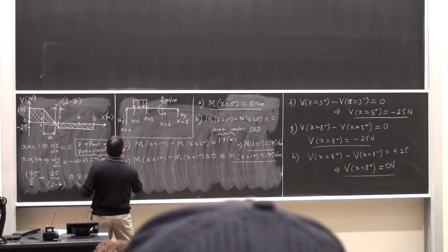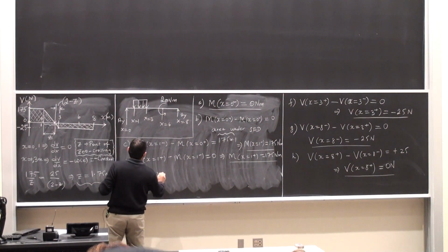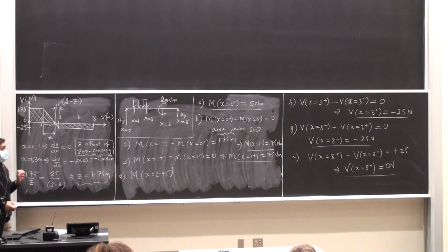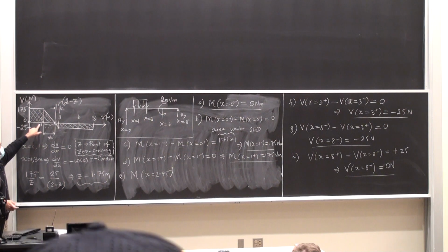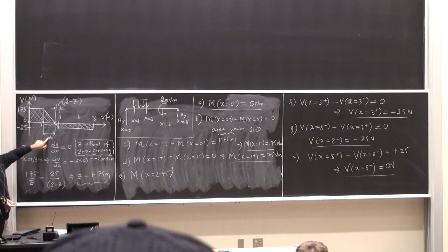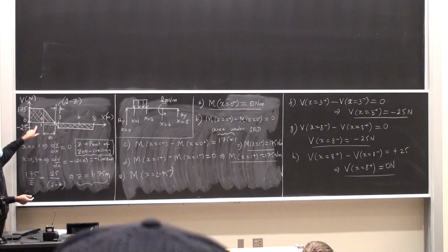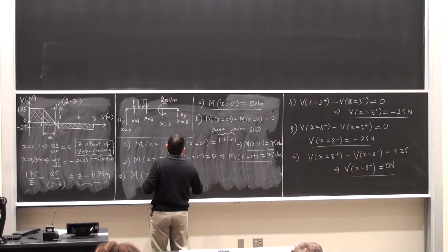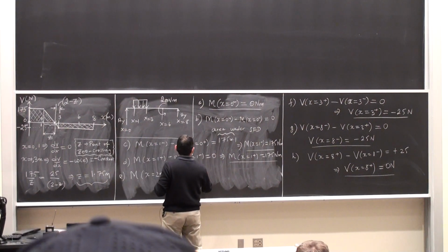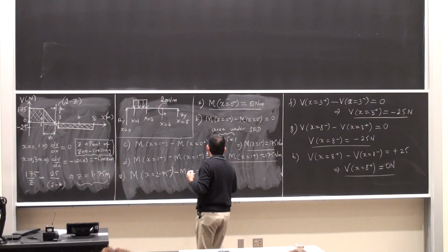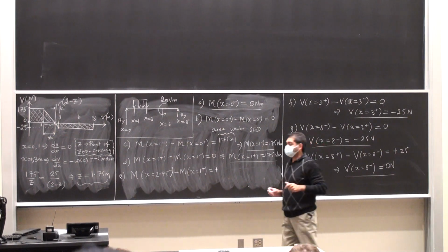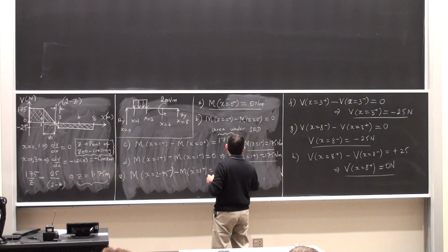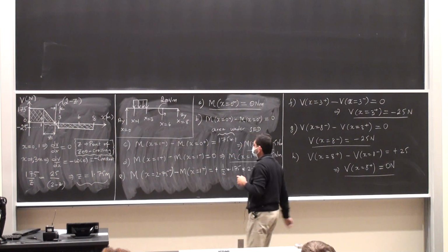Okay? So M at x is equal to 2.75 minus. 2.75, where do I get that from? 1 plus z. Z is 1.75. This distance is 1 meter, so 2.75. Minus M at x is equal to 1 plus is the area of the triangle, half times 175 times 2.75.